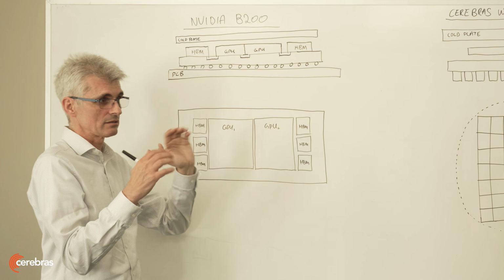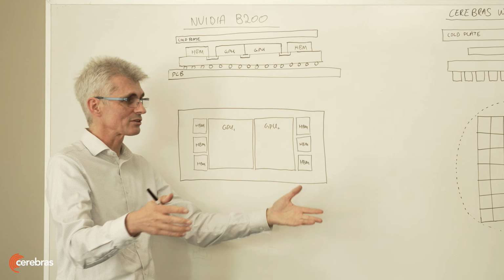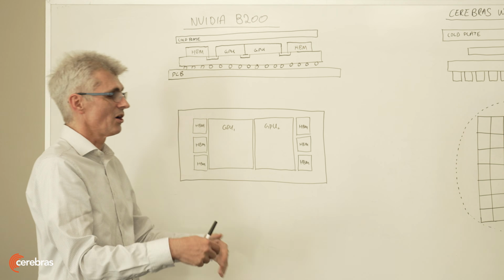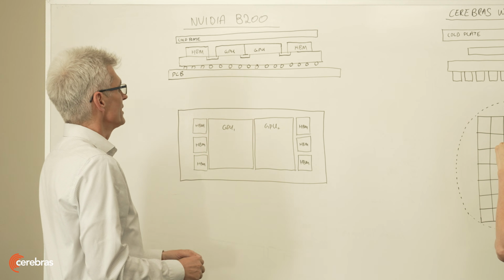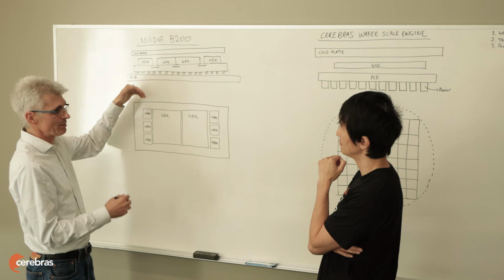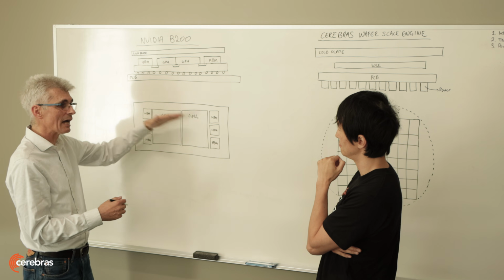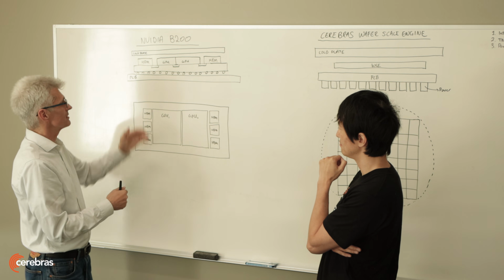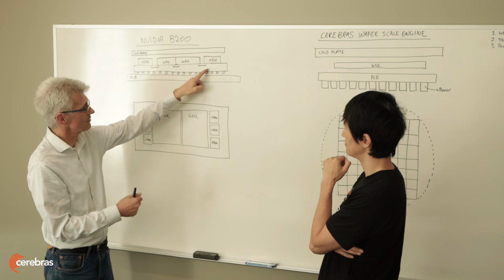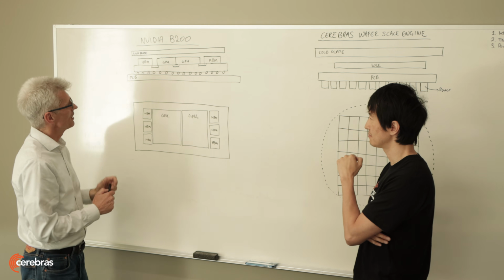So at the system level, you have printed circuit boards within your servers. On those printed circuit boards, you need to put some processors. And what people do is place the various silicon die that are manufactured on wafers onto package substrates. So here is one example of such a substrate.